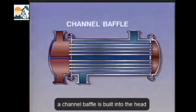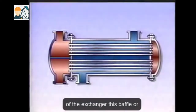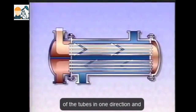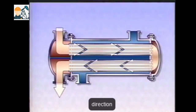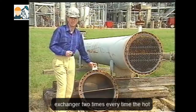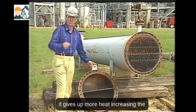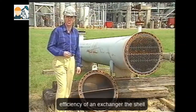To do this, a channel baffle is built into the head of the exchanger. This baffle or partition directs the flow through half of the tubes in one direction and through the other half in the opposite direction. Here is a channel head baffle that directs the tube side fluid through the exchanger 2 times. Every time the hot fluid makes a pass through one channel, it gives up more heat. Increasing the number of tube side passes improves the efficiency of an exchanger.